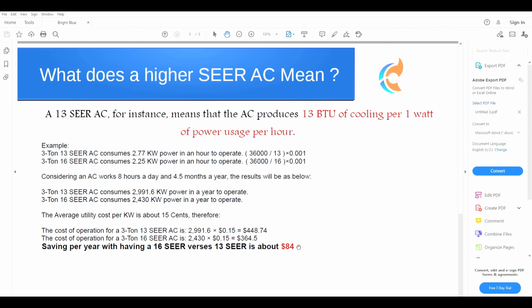I only recommend a higher SEER air conditioner for brand new homes, when they can put in a modulating variable speed air handler or a furnace with a two-stage, not even 16 SEER, like 20, 21, or some 26 SEERs that Carrier has. That's worth it. That unit is worth it. If you have everything high end, that's worth it.